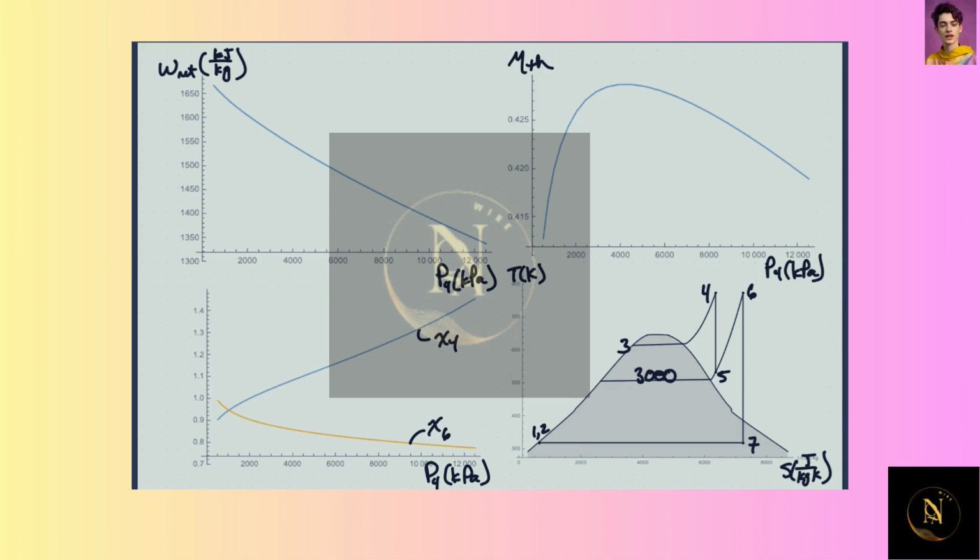Again, as the bleed pressure gets up to the inlet pressure, then we're not really doing anything. So if we're trying to optimize the power output for a given flow rate, we want to basically have the bleed pressure as close to the exit as we can. But if we do that, we lower the efficiency.